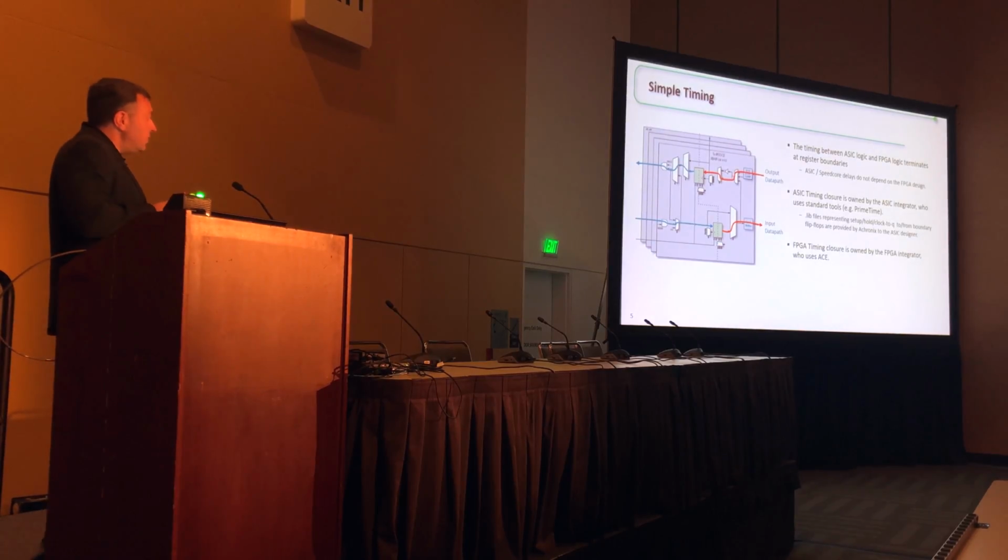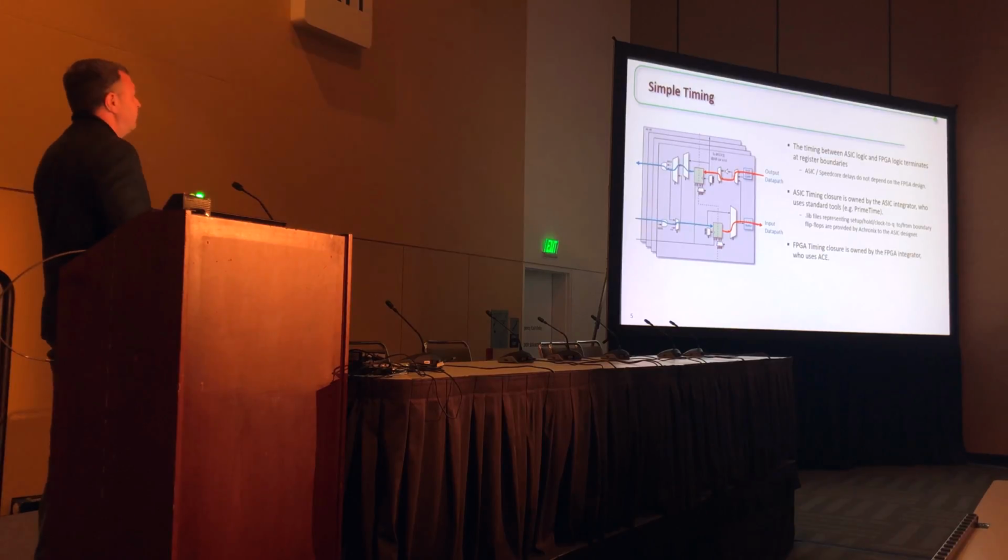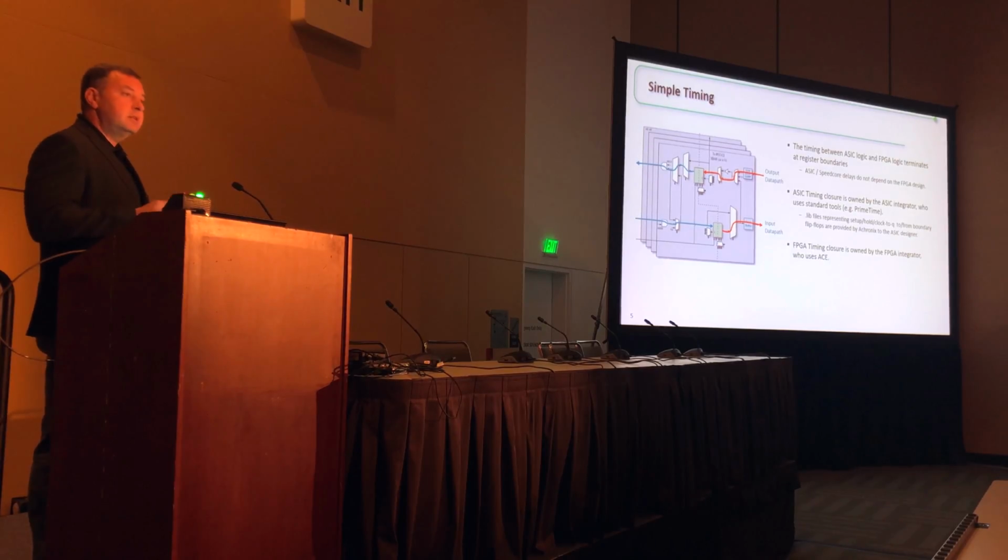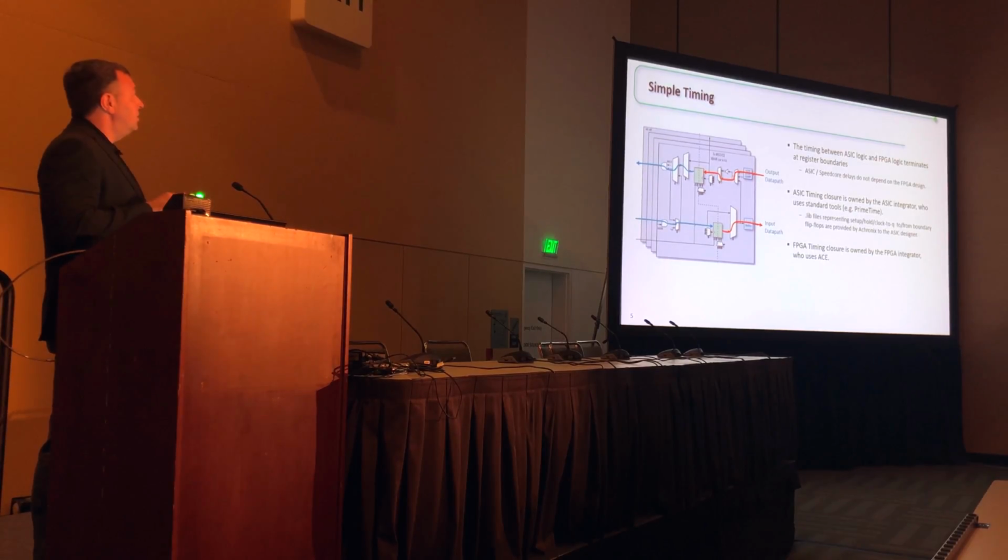So here we have something I'm referring to as simple timing. Think of this as the introduction to today's story. When we have simple timing, what we've done is enabled these registers. What this means is the ASIC designer, he's thinking about timing closure as beginning in this flop.